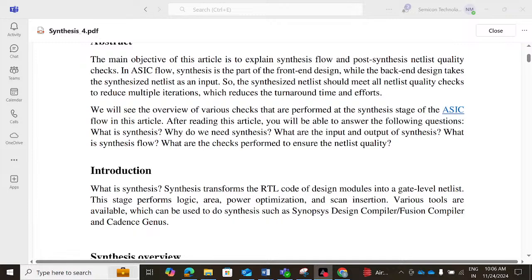If we are doing physical aware synthesis, when we enable the congestion and try to replace high pin porosity cells with low pin porosity cells, if the congestion optimization is not done properly, the congestion will pop up in physical design, and which will be difficult to close in physical design, which will again lead to multiple iterations in synthesis to replace high pin porosity cells with low pin porosity cells for minimizing the congestion, right?